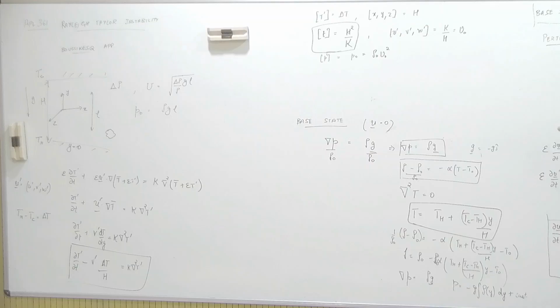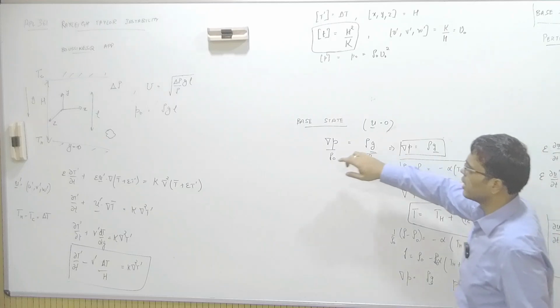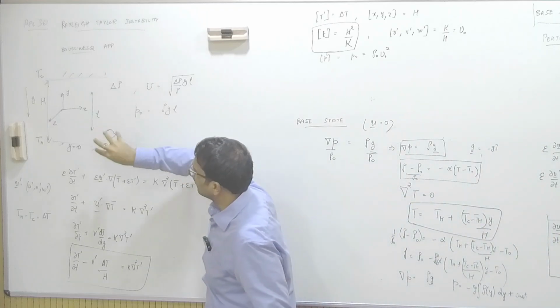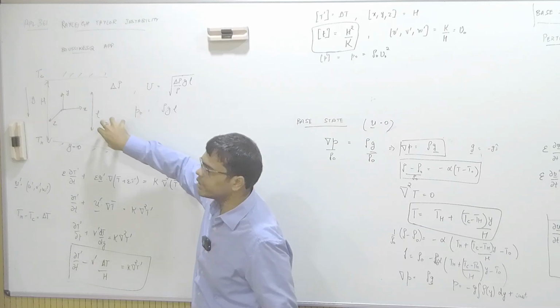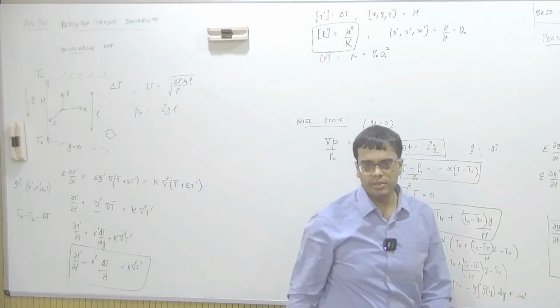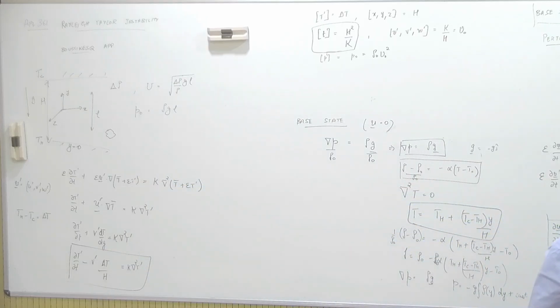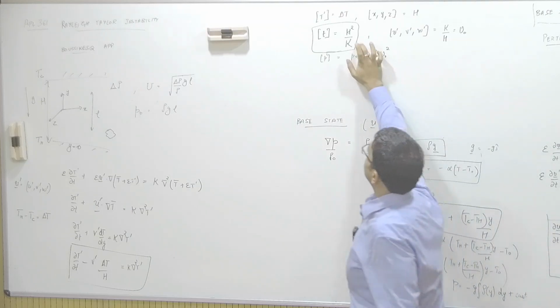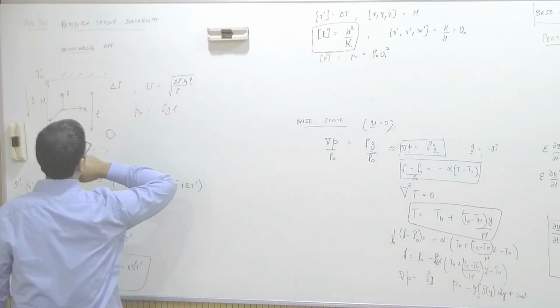And the other one, if you define a velocity scale and using that you define a time scale, what does that represent? That represents, okay, how long, if there is a blob of some velocity, how long does it take for this blob to convect itself upwards at a distance of capital H? Diffusion, convection, they are completely different processes. So that time scale is again physically very different from this time scale and the h square by nu time scale. Okay, we are picking this time scale.